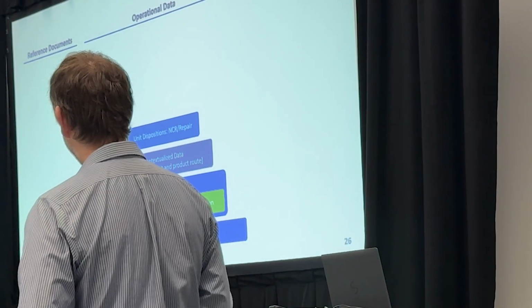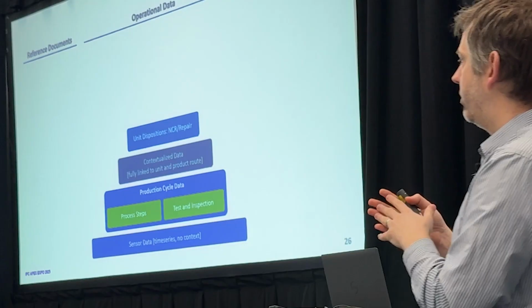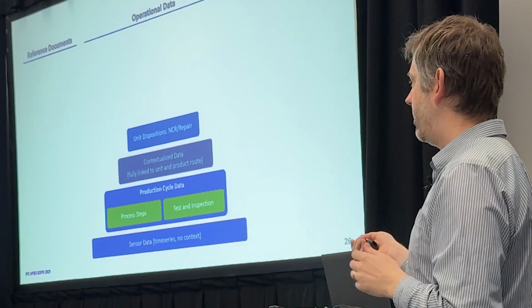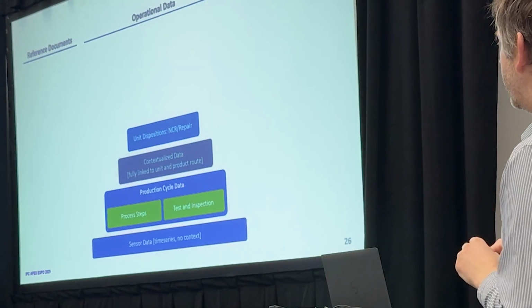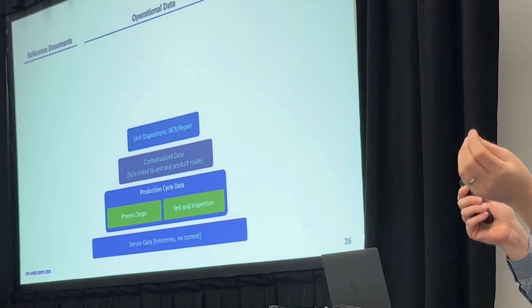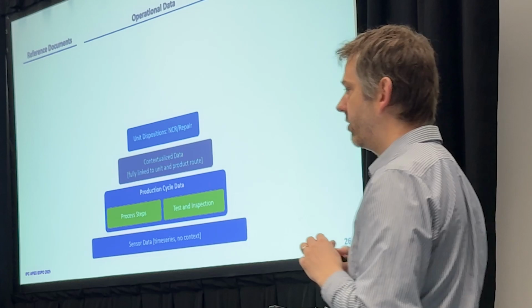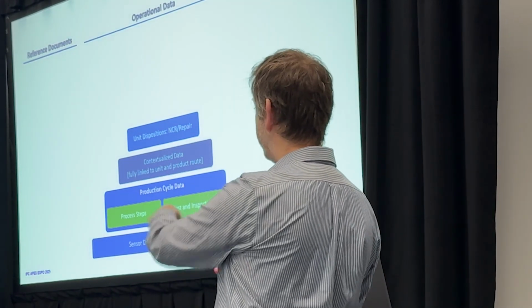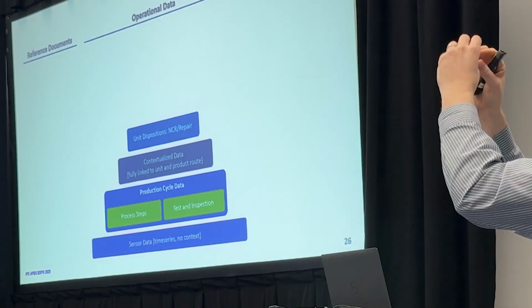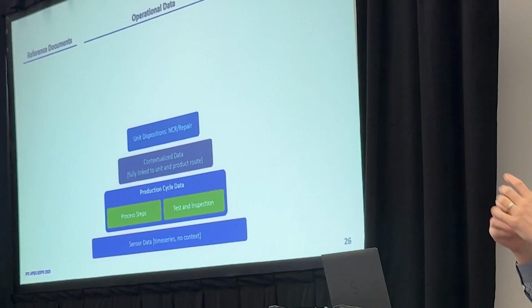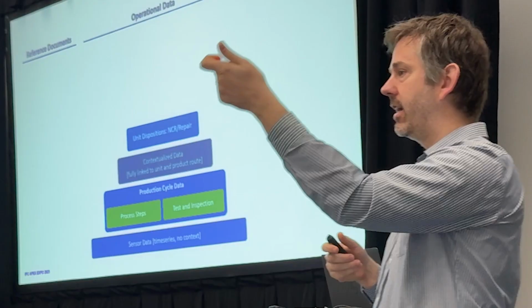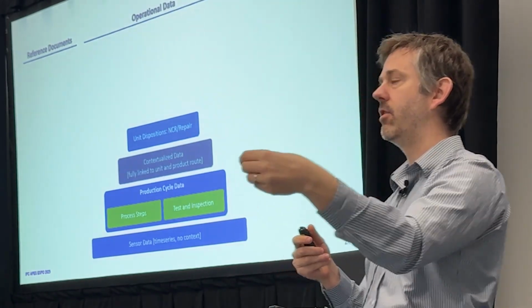But what I want to highlight here is that it's not the case that this data is fully contextualized to the product that's being built. Take a solder paste printer, for example. Not all solder paste printers scan the barcode of the unit that they're printing on and put that in with the data they're sending. So you know exactly that this data is associated with a PCB panel when it was processed. But if you wanted to look in your MES at all of the process steps it took to make a product from start to finish, you wouldn't necessarily see this data at that level, because that barcode link wasn't scanned. You don't have it in the MES, it was left one layer below.